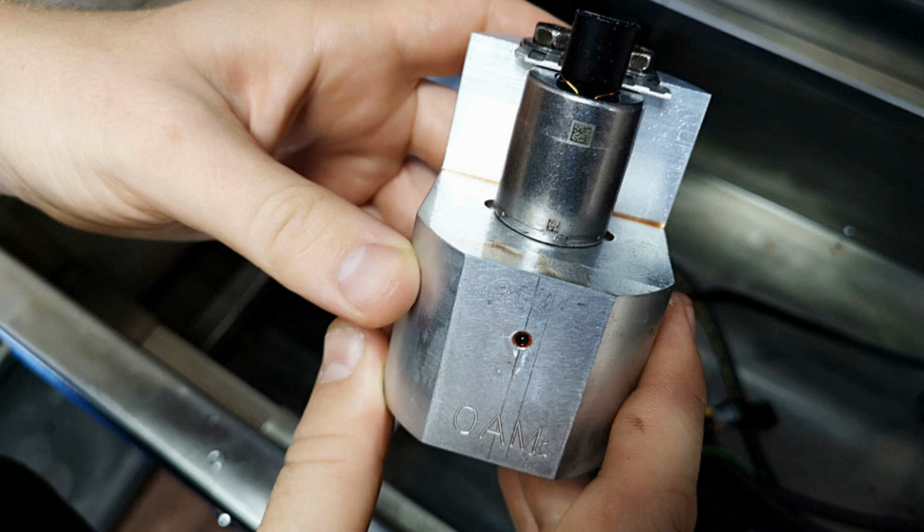In automatic transmissions, depending on the scheme used and the number of stages used in the automatic transmission, 4 or more solenoids can be used. It is important to take into account that the weak point of the car solenoid is its loop or cable connection to the electronic control unit. This forces motorists to replace these components with approximately the same frequency as the replacement of the solenoids themselves.